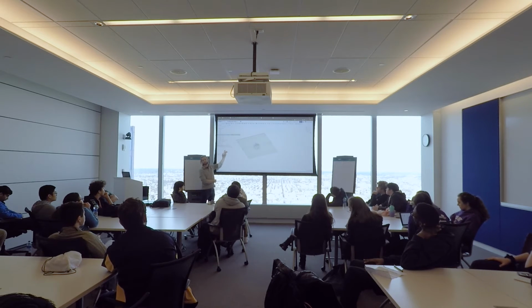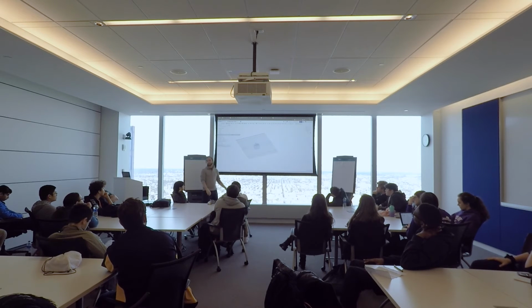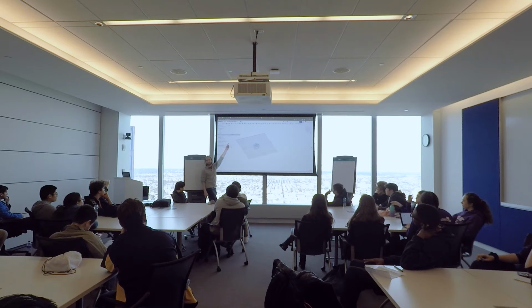So this is like a standard West Coast drive, which is ironic because 103 hasn't made a West Coast drive in like 3 years now. But it's fun to model. I have this wheel spacing, which is calculated using a chain center-to-center calculator. If you don't know, chain, depending on how many links you have, has very specific dimensions on center that you should use to calculate and define how your robot is designed.